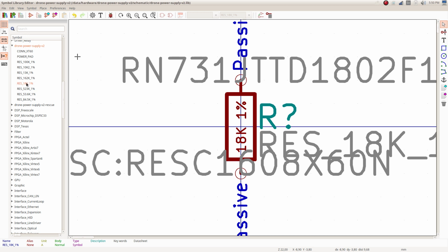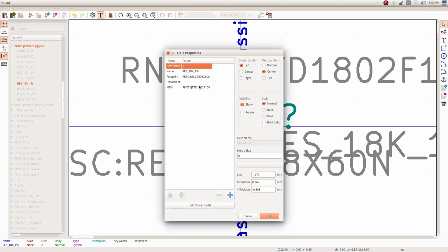Part of the reason for putting it together like this is that it allows reuse, and it also allows you to double check your library and make sure that all components are correct, and that all of them are bound to actual products which are purchasable. And when you export this into a BOM, you get the manufacturer number directly in the BOM.